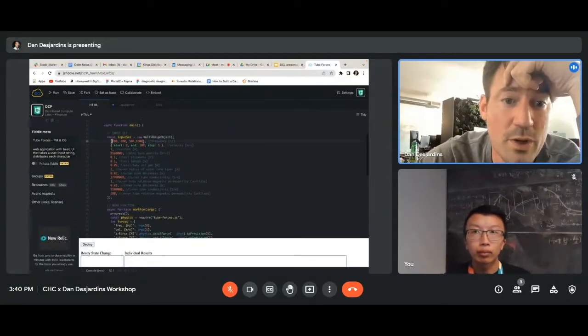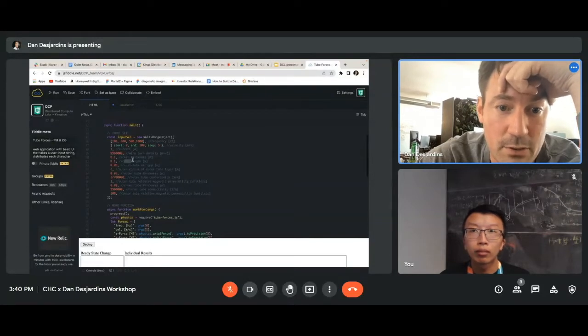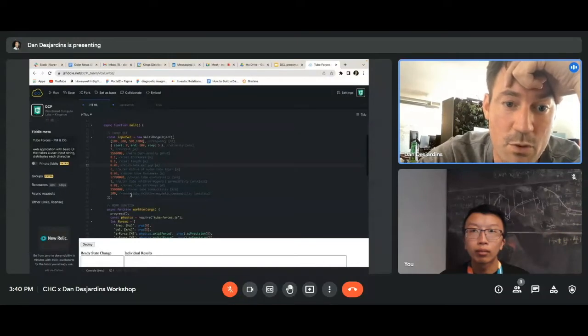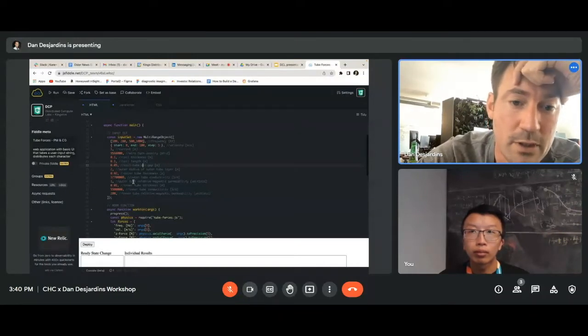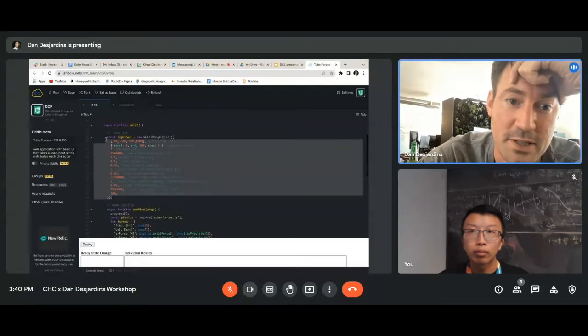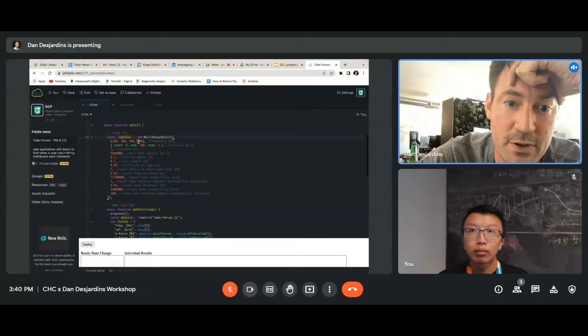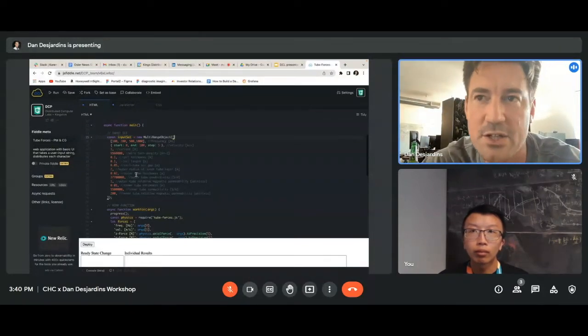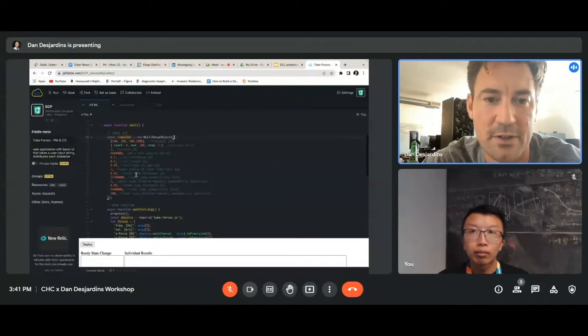And this is where I'm saying which frequencies: 100 hertz, 200 hertz, 500 hertz, 1000 hertz, which velocities, which wire turn densities, coil thicknesses, coil lengths, and so on. So I'm going to essentially calculate results for each and every one of these data points that I want computed. This is a very nice, neat, compact way of expressing it. So for all 4 of these frequencies, calculate all of these velocities for all of these parameters. If I were to unroll this range object, there's a couple of thousand computational points to perform. And if each takes a second, that's a couple of thousand seconds.